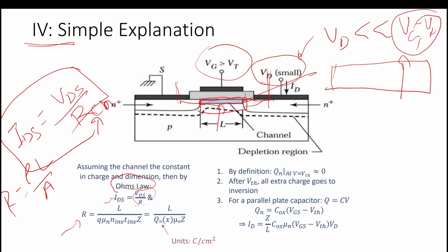The rho will come from the conductivity. Rho is nothing but resistivity. We know the conductivity is given by charge Q times mu n times n. Q times mu n times n, this is the conductivity. Q is the charge on an electron, and mu n is the mobility of the charges, the mobility of the electrons.